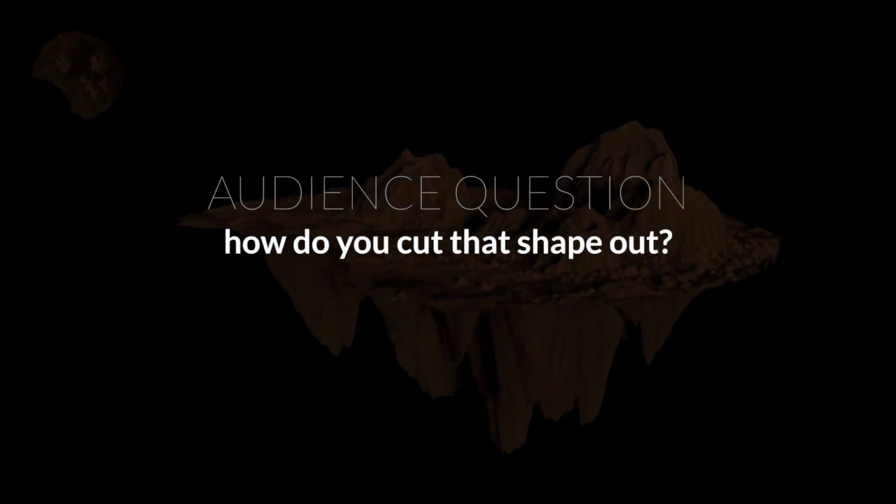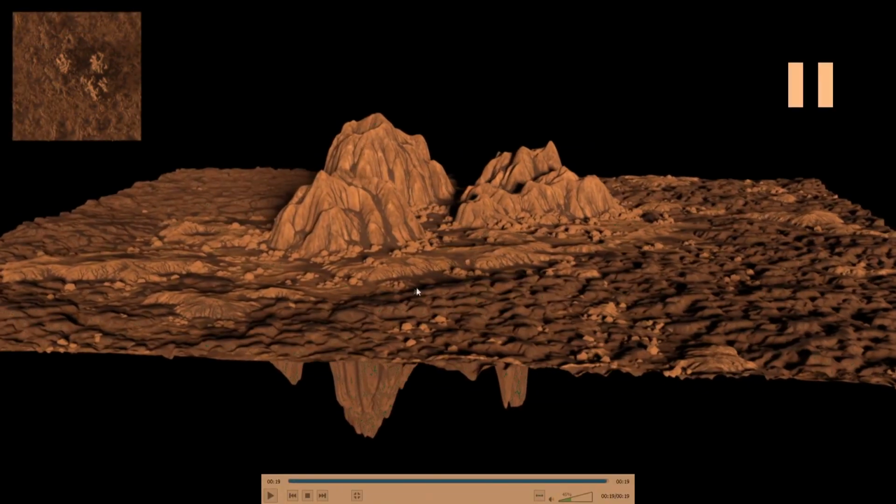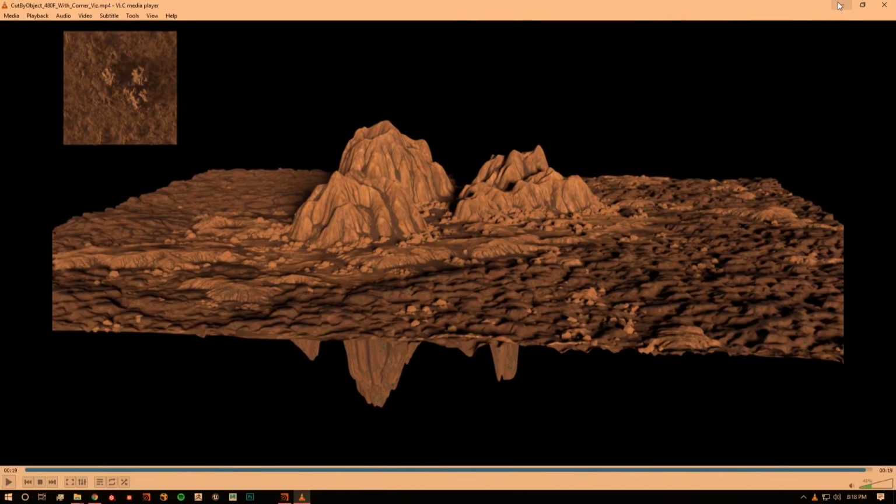So how do you cut that? Let me show you that. Is that just another node? No, it's like, as I created a mask by using an object, you have the Heightfield Project node, right? Yeah. So you have the Heightfield Cutout by Object node, where you can cut out by object, but it is available in Houdini 17.5 because it's only in the recent version. You can just plug that into the second input of Cutout by Object, and it will only keep the area which is covered by that object. So now you know more about how to get around the dependency on square heightfields.